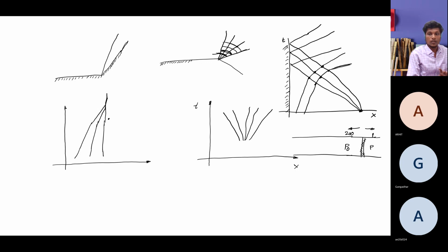But you should be clear, right? When it is a shock tube, the rightward running creates a normal shock and leftward running creates an expansion wave. But in the expansion wave, again, if you draw the characteristic lines clearly, there will be another family of curves that does not influence anything in the flow field. But you can draw, and it will be helpful while solving for the properties of the flow field at that point. You can get much more clarity of these kinds of waves by studying the shock tube in detail. You can find it in Anderson's books, John D. Anderson.